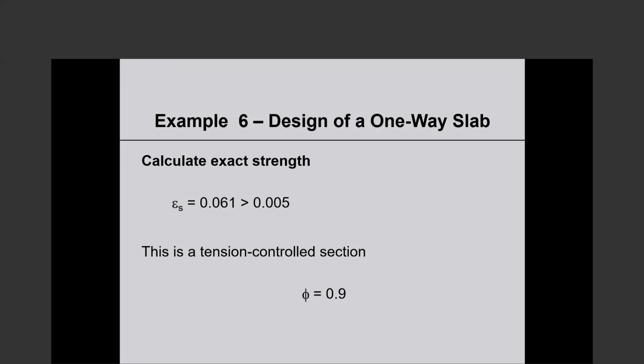Yes, it is allowed to the best of my knowledge, but I will tell you, with low strength concrete and high strength reinforcement, you are not getting full value. High strength reinforcement requires high strength concrete if you are going to get full value out of it.